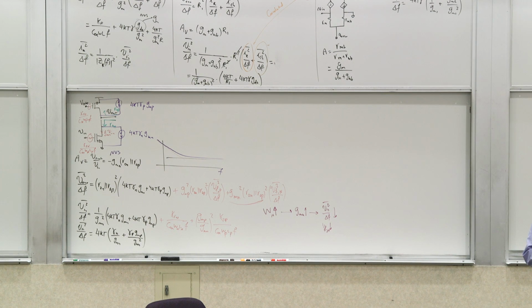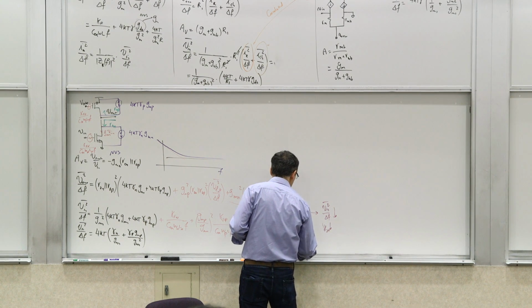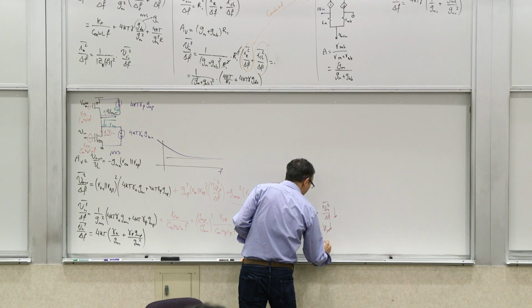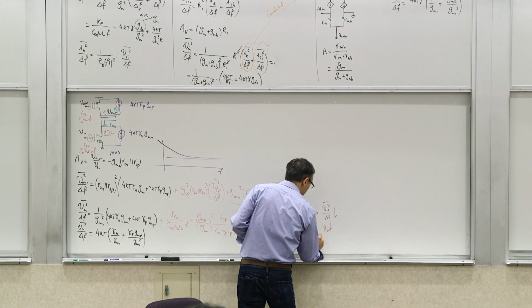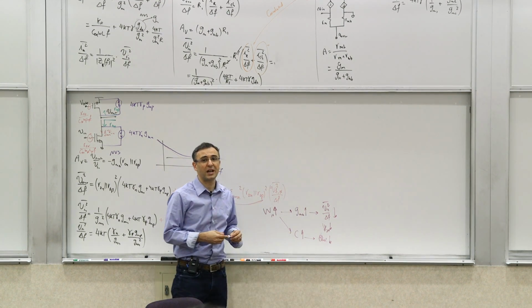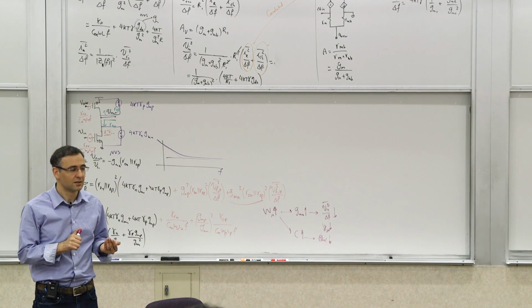What is it that we are losing when we do that? Speed, exactly. Why are we losing speed? Capacitance, right? So the capacitance is also going up. So this means that C is going up, which means that the omega 3 dB, or let's call it bandwidth, is going down. So there's a trade-off there between speed and noise as well, right?